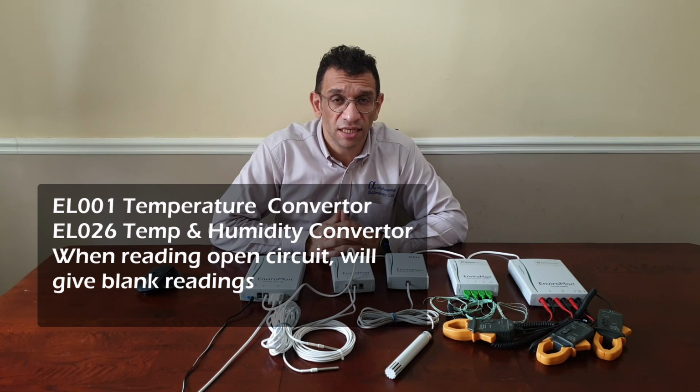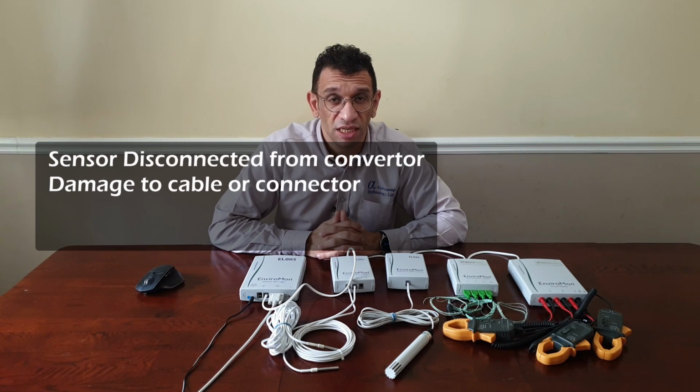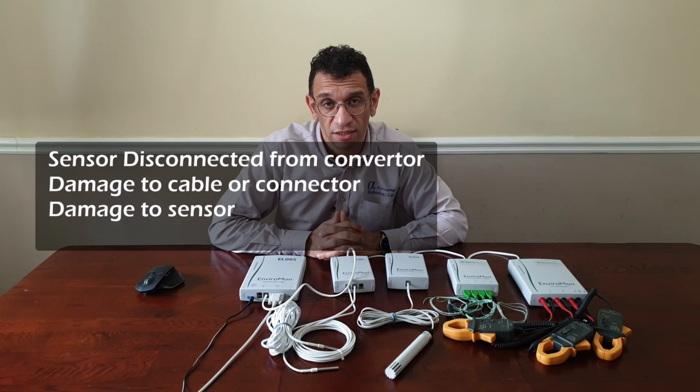Now it could be that the sensor is disconnected from the converter, or it could be that there is damage to the cable or the connector or even the sensor. So have a visual inspection of the cable and the connectors to make sure that they're in good working order. Now I'll do a separate video about crimping connectors, so make sure you check that out.